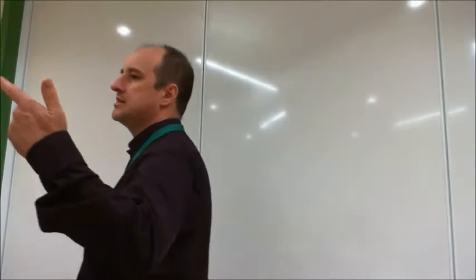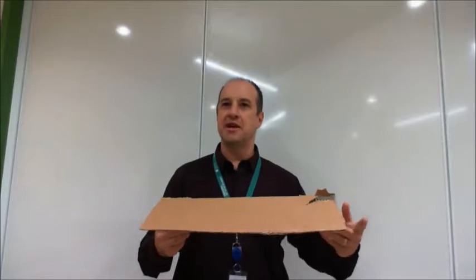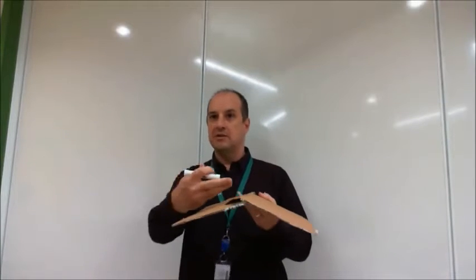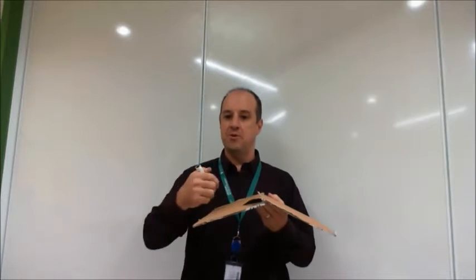Yes and no. If you have a building, let's say this is the building, and you don't know if they're going to build it that way around or that way around. Then yeah, you take the worst case because the wind could blow from any direction. On the other hand, if you've got a massive roof and you know it's going to be in line this way, and the highest wind comes from the west in this direction, you might have to make this side of the building stronger than that side, and that saves you money. For most small structures, you're going to pick the worst case wind and go with it.